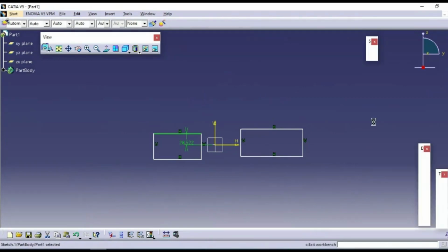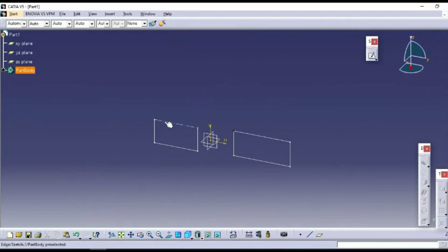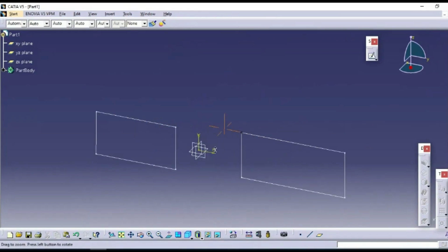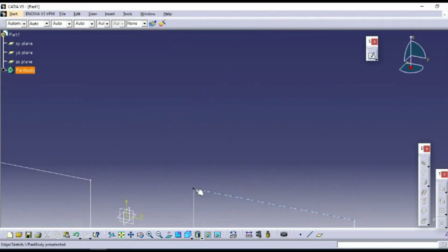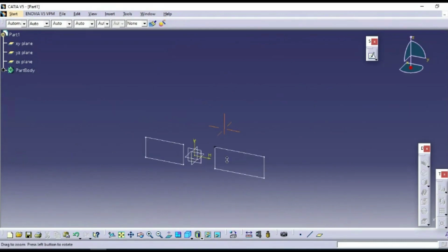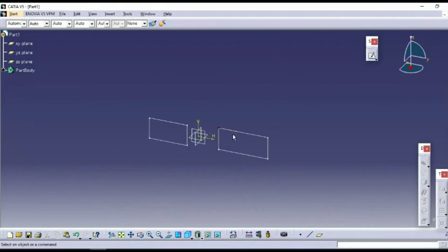You can see now. You see, it is completely closed. So all the points are in white color. But this profile, you see, it is closed. These 3 points, so it is in white color. It is not closed, so it is in black color. So these open profiles cannot be used for the 3D design.